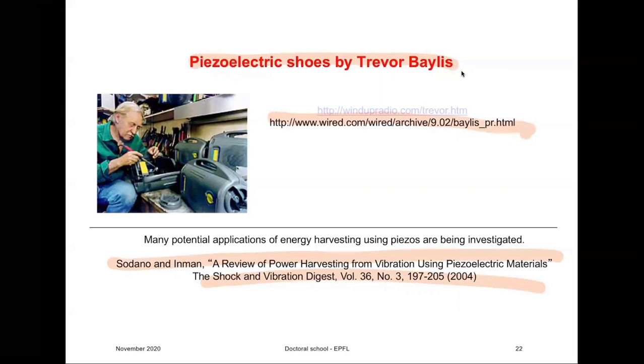One thing that you should remember: piezoelectric energy harvesting cannot solve any energy problems. It's too small. What it can do is provide you small amounts of energy where it is immediately needed, so that you either don't have to use batteries, which you have to replace all the time, or you can charge the batteries, which can remain in place.